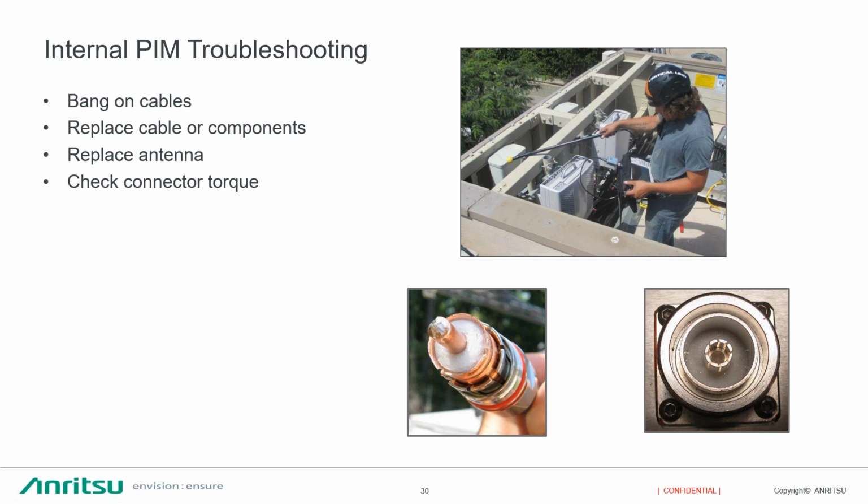So in terms of, do you have to climb the tower for this? Well, yeah, you do. But at least you know that it's internal and you're not going on a wild goose chase across different places and different things. Your site might still be live, but you've just turned off the sector so that no one gets radio burn. Again, just follow the safety protocols when you get to this point of troubleshooting internal PIM. Everyone's got them, so I'm not saying anything that anyone doesn't know here.